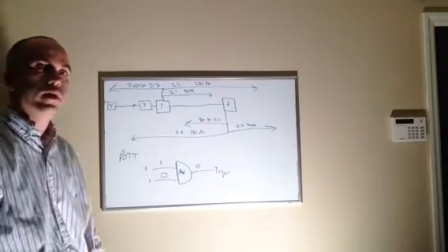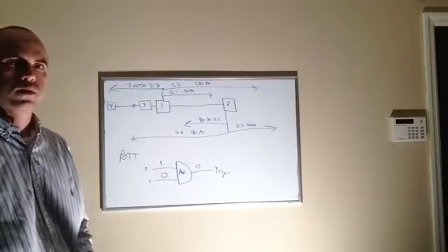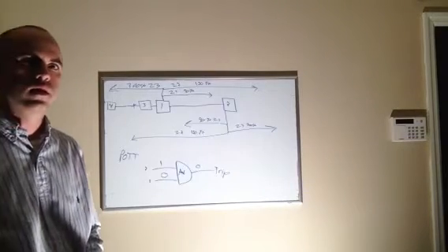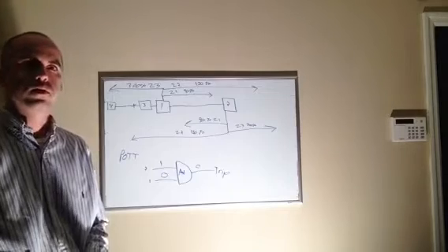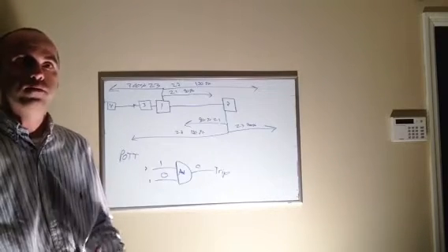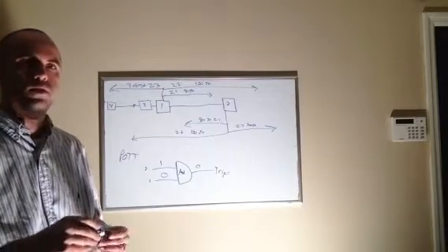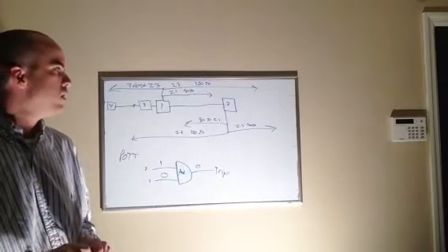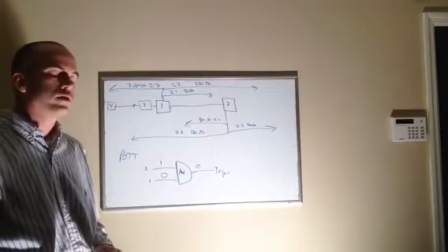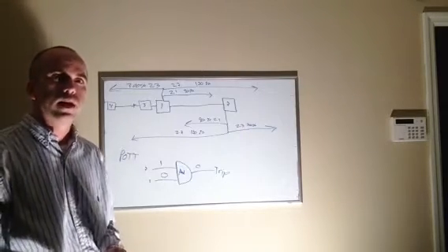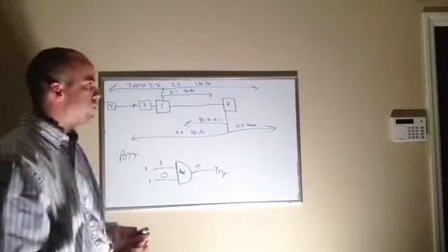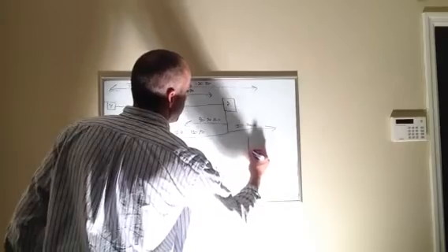in comparison to how carrier works. They both accomplish the same thing: high-speed tripping on 100% of the transmission line. They work differently. Most of the new installations that I have personally seen are using POTT as opposed to powerline carrier. One of the big ways that you can tell is that a powerline carrier is going to have, because it's on the line, if you were looking on a single line diagram, you would see something like this coming into the breaker.